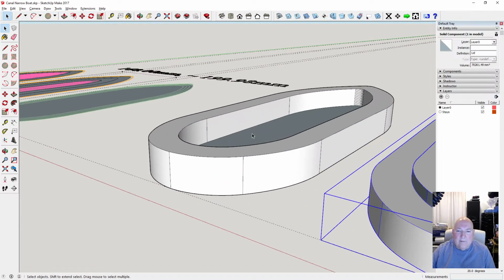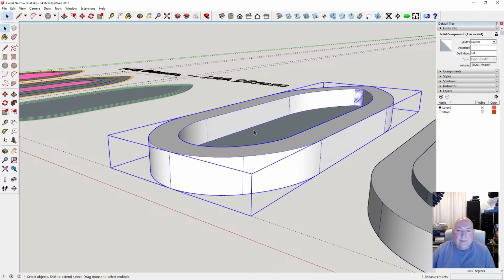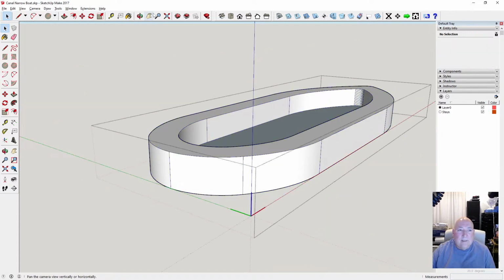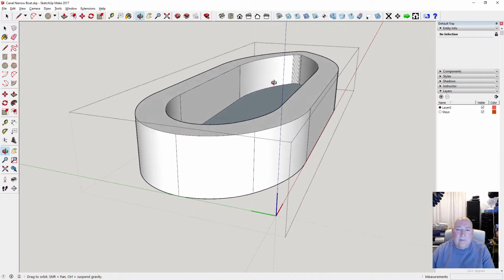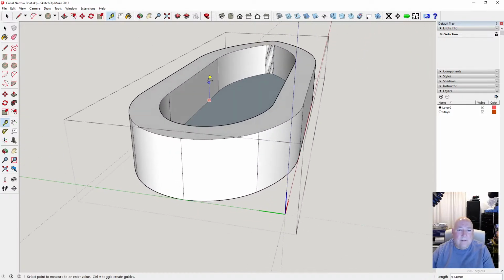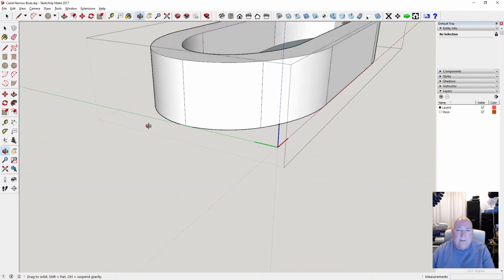Right, we want to make this the right sizes, so 20mm thick. So these are still on the 12mm. So let's just do that. Let's do another 8mm on top of that. And we said the bottom was going to be, that's 18mm. So 2mm, but we said we're going to do 3.5mm thick, so we need to go up 1.5mm. Okay, so that leaves us with 16.5mm, so we've got 3.5mm bottom. Yeah, that's fine as it is.